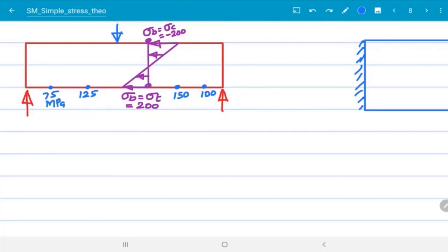Only one type of stress. All are bending normal stress only. So we need not worry about the other categories, torsion, transverse shear stress and others. We need not calculate the equivalent normal stress either. Directly, since only one stress is available, we can select any one number.